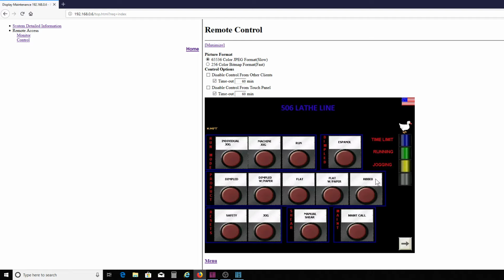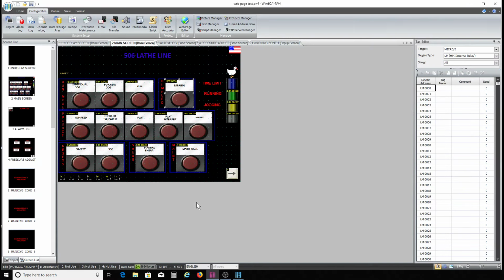So you need to actually think about that before you start controlling a machine. Controlling your house and controlling a machine that can hurt somebody, two different things. So keep that in mind. You don't want to be turning off and on a machine in a plant from 50 miles away without seeing it. You want some kind of a visual monitor or some kind of personnel control before you start doing things like that. You got to really think that through so you don't get somebody hurt. But anyhow, that'll give you something to think about.